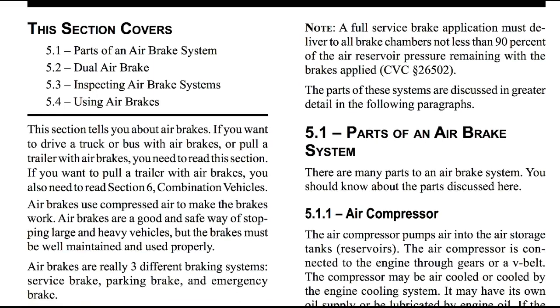Note: a full-service brake application must deliver to all brake chambers not less than 90% of the air reservoir pressure remaining within the brake supply. The parts of these systems are discussed in greater detail in the following paragraphs.